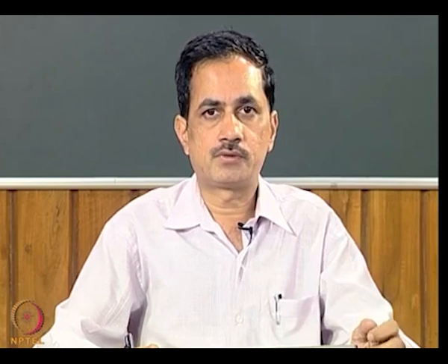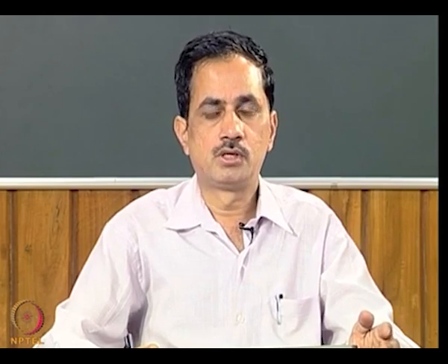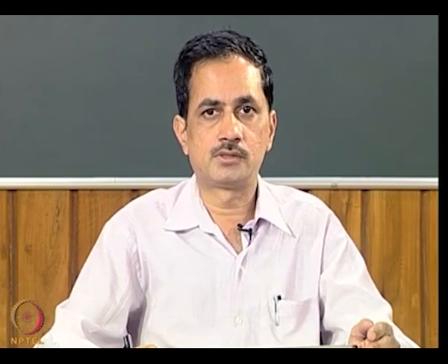With a very simple case of a simply supported rotor, we showed the analysis of how modal balancing can be used to balance the rotor up to the second mode by using two planes, which balances not only the first mode but also the second mode. In the subsequent lecture, we will take up another method which is more advanced and more powerful, the influence coefficient method for flexible rotor balancing.